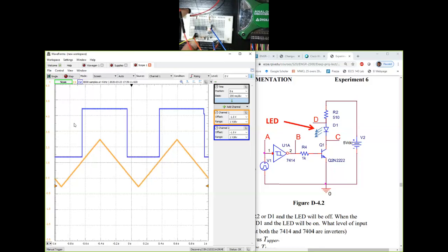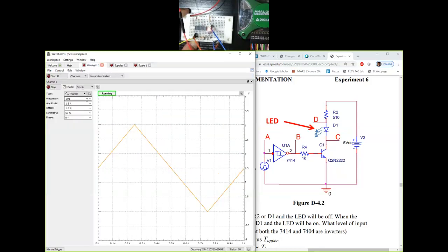Let us see what happens to this LED if you increase the speed. So let's go back to the WaveGen and make it 10 Hertz. I hope you see that the LED is now blinking faster, 10 times faster. Can I look at it when it is 20 Hertz? I can see very comfortably that it is still blinking. In fact, if you go to 50 Hertz, then it kind of remains on.